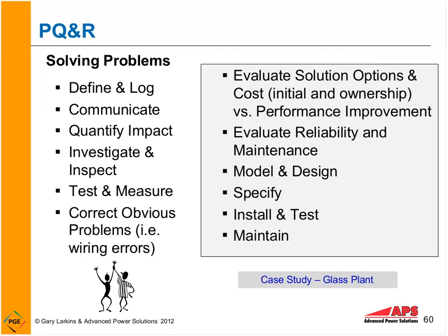Now, for an example, in a glass plant, we were able to go out and put in adjustable speed drives where they had standard motors. We were able to put in adjustable speed drives and back up the controls because they were seeing that when a breaker operated from the utility, the glass plant equipment would go down. They'd have molten glass that would harden in their equipment. So in this case, although the side benefit was energy efficiency, their primary concern was the equipment going down, uncontrolled shutdowns. So we were able to install adjustable speed drives that could restart on the fly, back up their control systems, and we actually used that to solve the problem.